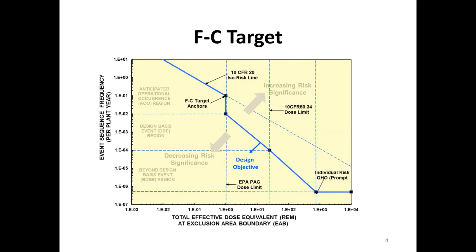Okay, I agree fully with that. These are the kind of questions this NRC project is trying to explore to get a better handle on. And as you said, in a nuclear power plant, at least in the light water reactor, seismic design, like thicknesses of outside walls and things like that, is generally governed by a lot of other factors also, tornado design, pressure loads. Yeah. But you have to think where you can take advantage of, or where it's possible to do this relaxation.